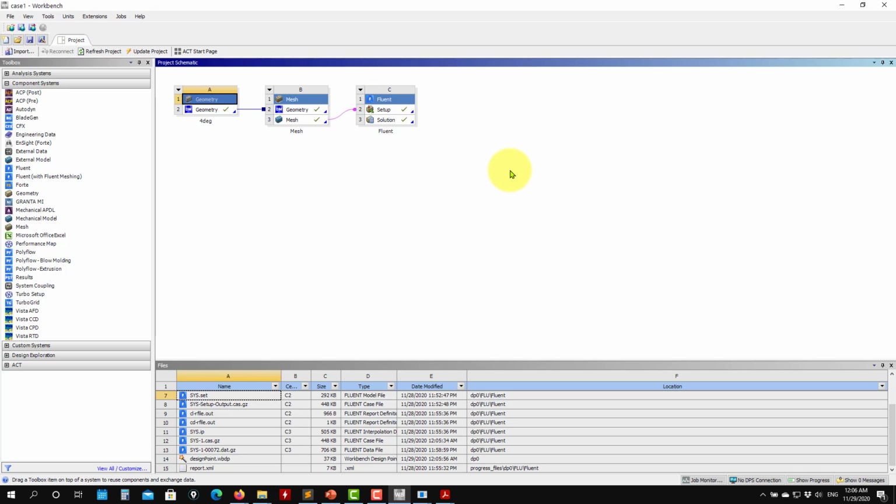So I want to run now for 0 degrees. What I can do is modify the angle here and rerun everything, but I want to clone this one. So you select everything, you go here, duplicate, and then you are going to duplicate this case. All this setup is exactly the same. You don't need to change anything. The only thing you need to change is the angle here.